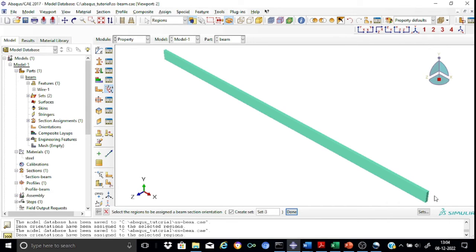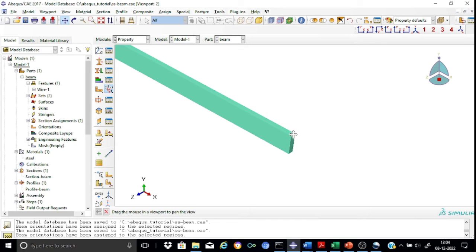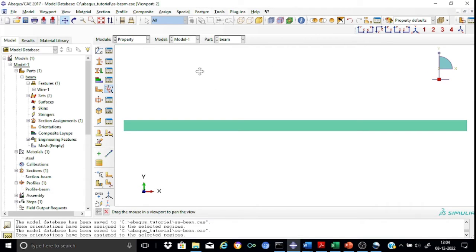Now in the isometric view, you can zoom in and translate to see the cross section. So the larger depth, and you have the 50 mm width and the depth. If you find that the dimensions are interchanged, you have to go and correct it. In the present case, it's all right for us. This is how you should check the cross sectional orientation, and it's a very important part because the calculation of the stresses, the deflection, etc., depends upon the section orientation.